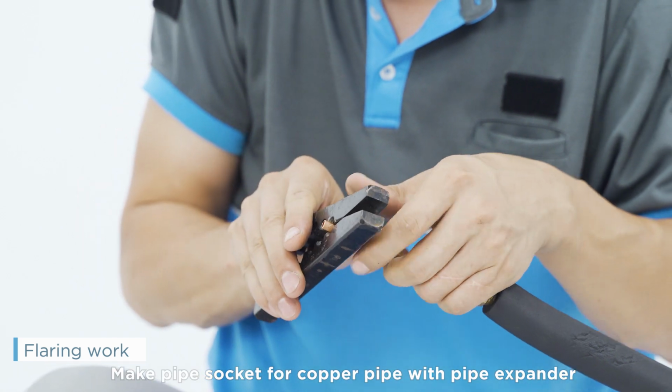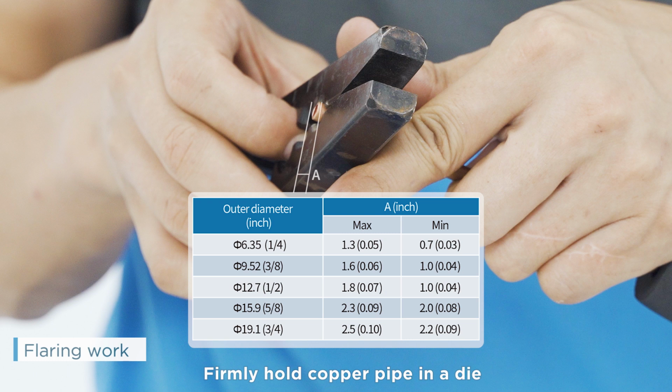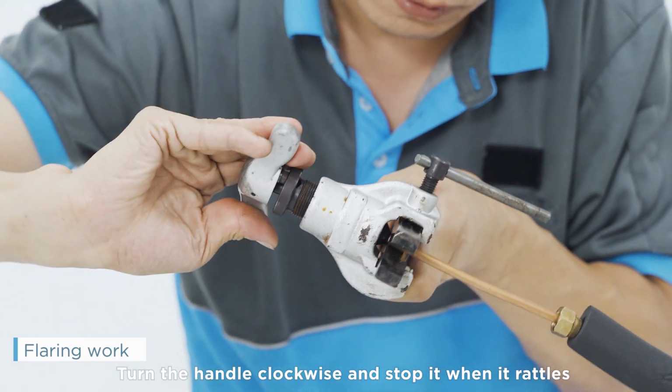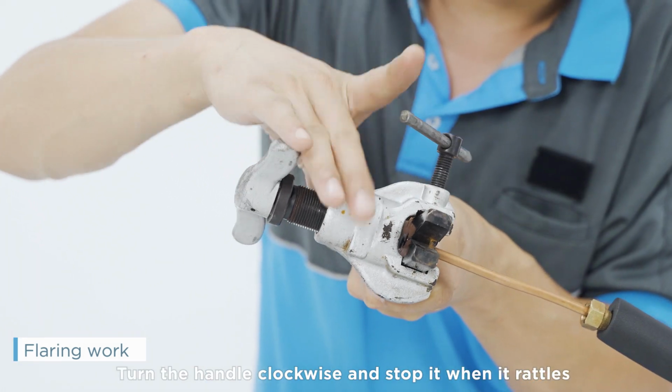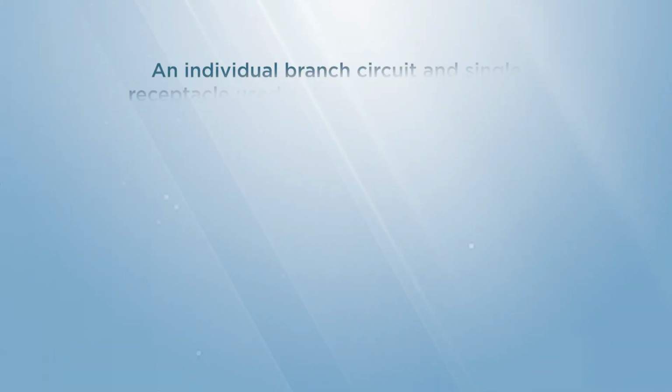Make pipe socket for copper pipe with pipe expander. Firmly hold copper pipe in a die in the dimension shown in the table. Fix flaring tools. Turn the handle clockwise and stop it when it rattles. Pipe socket should be level and uniform, free of crack. Wire stripping.